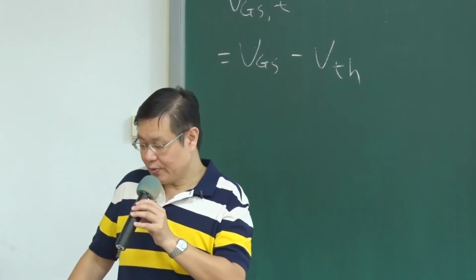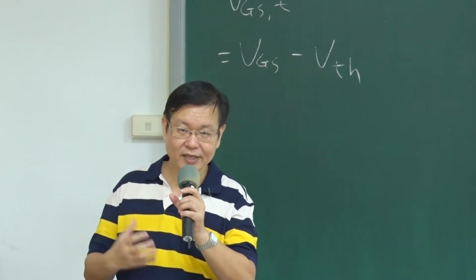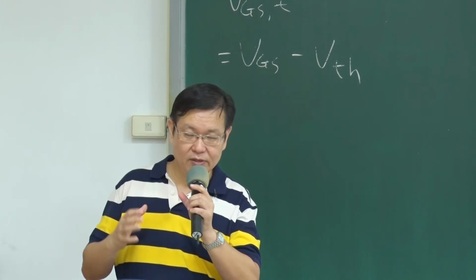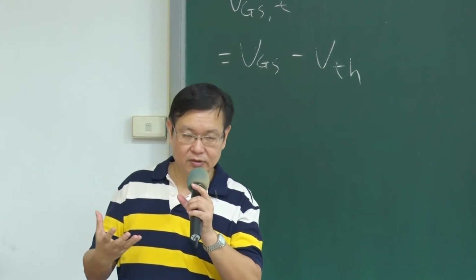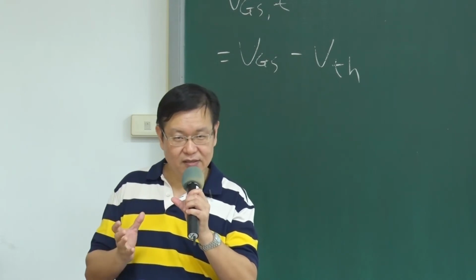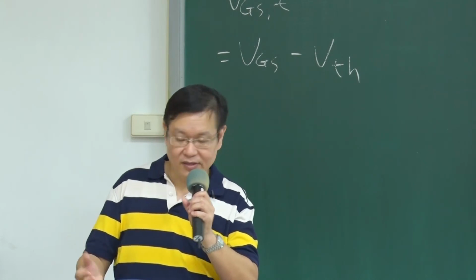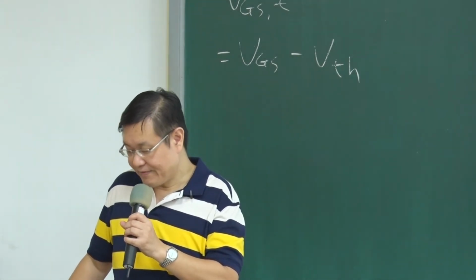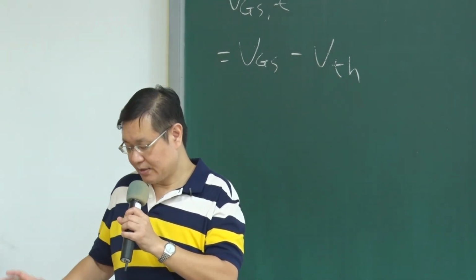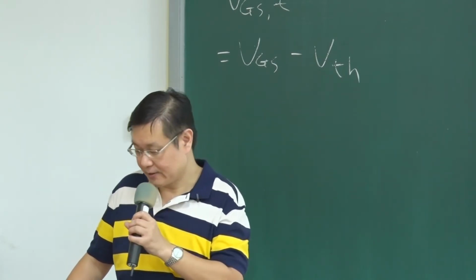Okay, so now after the fabrication of the CMOS chip, you get a device back. So the IC part is workable, no problem for you. However, the MEMS part before the releasing is still fixed on the surface. It's not movable, so it's not working. So it's important after the fabrication of the MEMS CMOS chip, you need to do a releasing process.